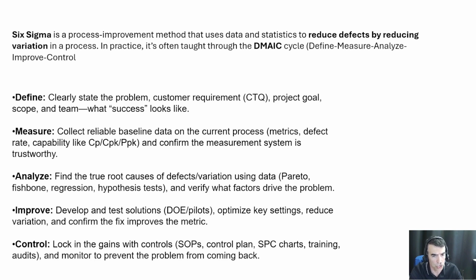You identify the variables in the process that would impact this OD variation, for example your pressure at the die, your temperature, or your water bath distance, and do a DOE. Then you look at your signal, that is the OD measurement, and analyze the data to see how you can optimize it to reduce the variation.